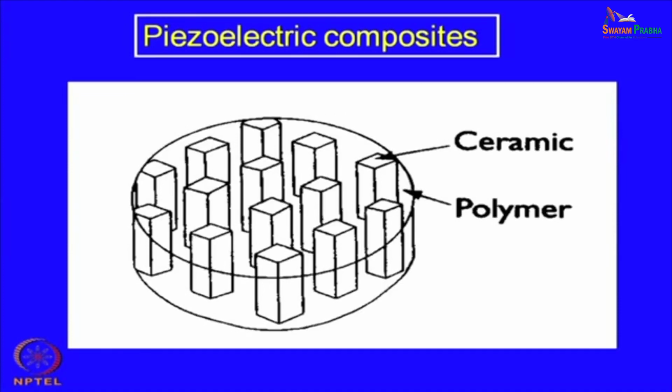But although ceramics have a high piezoelectric coefficient, they have a very poor mechanical property, particularly their elasticity is very low and they are quite brittle materials. So, one cannot stress them to a large extent, and therefore, you have a limited application.